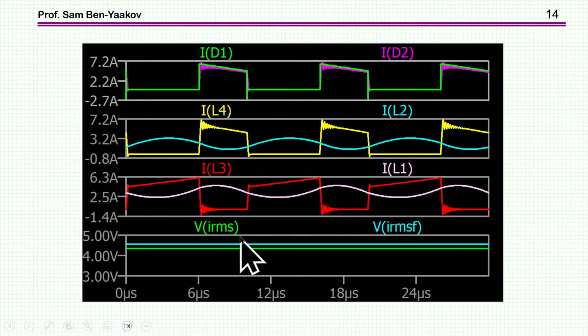And here are some more waveforms. What I'm showing here is the primary inductor current in the two cases. Well, the square one is the Flyback, of course, and this smooth one is the Sepic. And here is the current of the secondary inductor, the output. Again, the current is very typical here in the Flyback, while here we see it very smoothed. And this is again because of the leakage, which is sort of smoothing the operation and averaging it out.